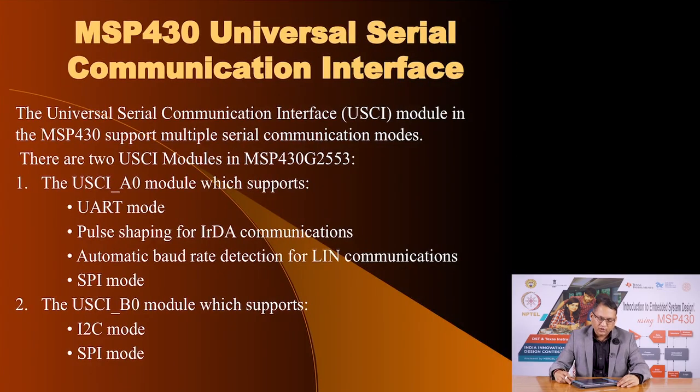Now, let us look at the serial communication capabilities within MSP430 in the context of these 3 protocols, and we will see how the serial communication peripheral on MSP430 allows you to select one of these 3 protocols and so on. Now, there are 2 serial communication interface modules in MSP430 G2553 that we are using, and they are called universal serial communication interface.